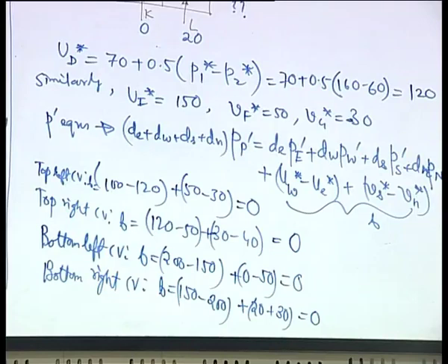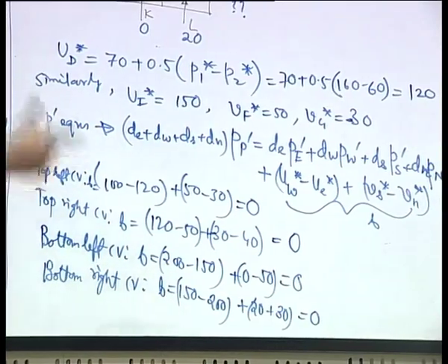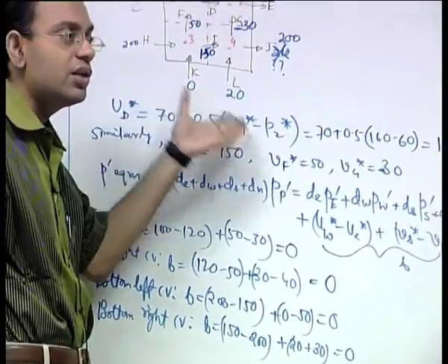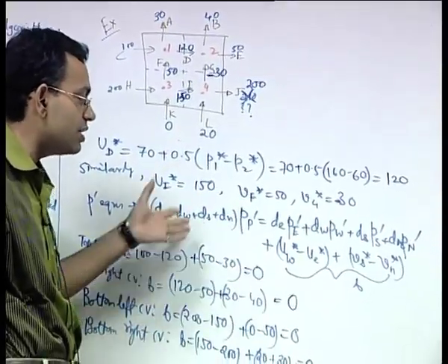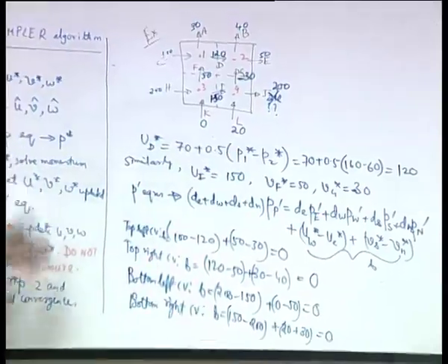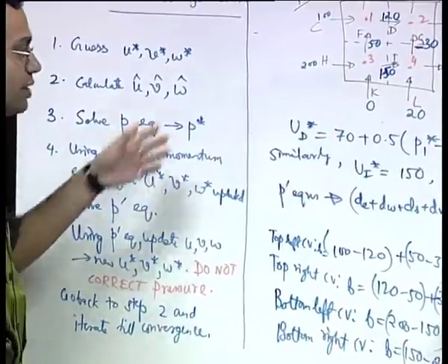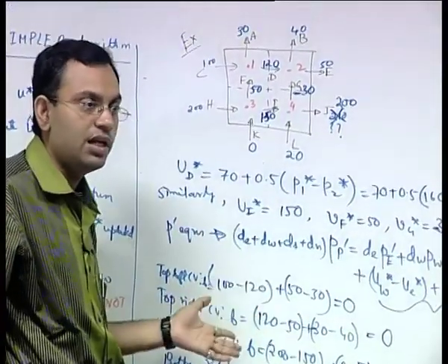So, we have already got the converged velocity fields, we have got the pressure corrections are 0. Even if the pressure corrections were non-zero, that is even if the velocity field was not converging at this stage, you still should not use the pressure correction to correct pressure, that is very important. But in this particular problem in one step it has converged, so no such possibility arises.